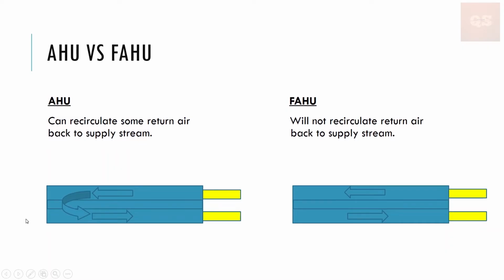The air from outside flows into the supply part. There will be a lot of filters, then your cooling coil, fan, and motors, and the air will slowly move through all these filters, fans, and cooling or heating coils, and then go into your supply duct. From the supply duct it is transferred to the different rooms through the various grills and diffusers. From the rooms, this air will go back to the return grills or return diffusers, then move into the return duct and go into the return part of your AHU.